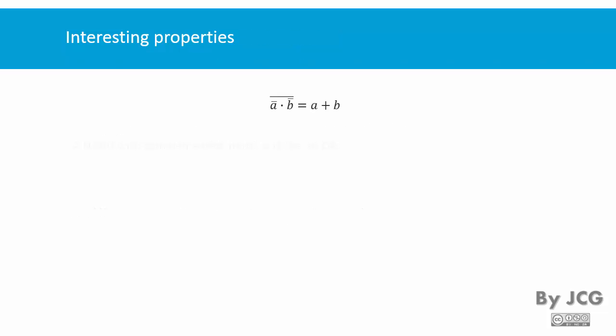And we also can invert the individual variables. Here I'm going to clarify it a little bit. The normal function of a NAND would be (A·B) inverted. If we apply theorem 8, then we know that this would be A inverted OR B inverted.